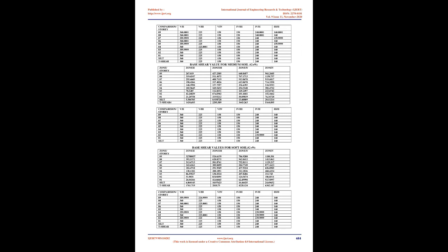As a result, the flexible side of the building, the edge of the building closer to CM, experiences larger displacement than the stiff side, the edge of the building closer to CR. If not designed to accommodate these excessive deformations, the columns on the flexible side may fail and lead to collapse. 3.5 The size of buildings.